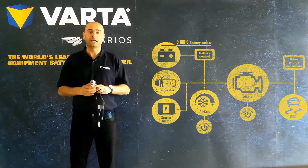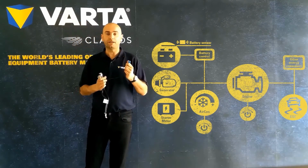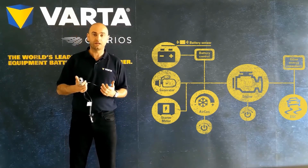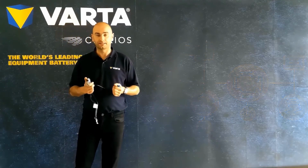The IBS has a reference supply voltage to the sensor. When replacing a battery, it's vital to perform the correct procedures to ensure the battery receives the correct charging profile and ensure all electrical consumers have been correctly reset.